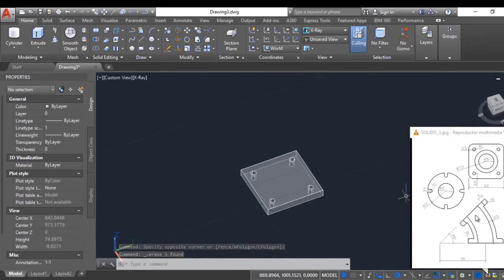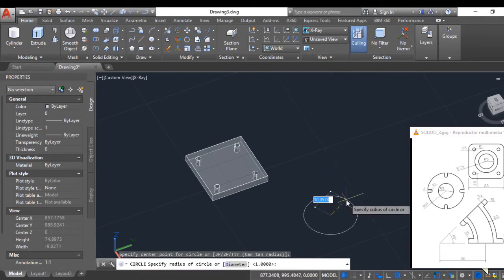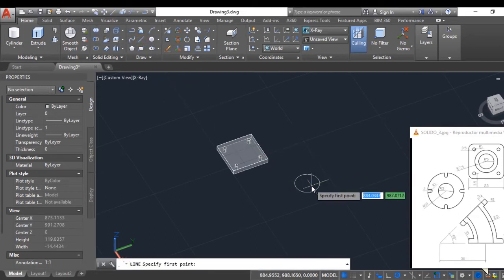Right. We see that they are with two radii, a radius of 5, 10 and 7.5. We are going to make the radii of the circumferences. We are going to draw the radius of 7.5. I move it. And from the center, a solid has to be made with an angle of 45 degrees. The shape will rotate circularly. So, we are also going to help ourselves with another line here in the center.